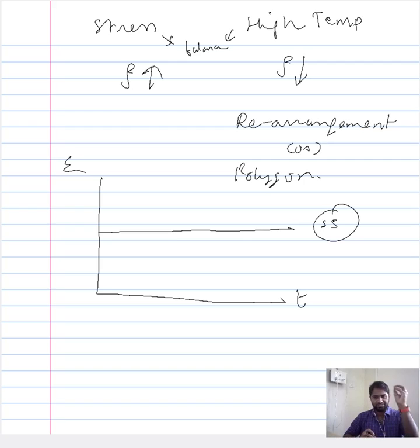The stress increases the dislocation density and it impedes or restricts the plastic deformation. However, the high temperature decreases the dislocation density by annihilation and by polygonization or rearrangement. This rearrangement essentially forms the low angle grain boundaries or the sub boundaries, thereby accumulating the existing dislocations and leaving room for new dislocations to form. Now, in addition to that, when you keep on holding the material at high temperature, even the different low angle grain boundaries or sub boundaries move and coalesce even more, sufficiently reducing the dislocation densities. So all these are possible because of the high temperature.